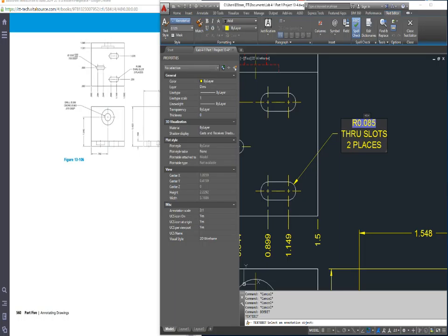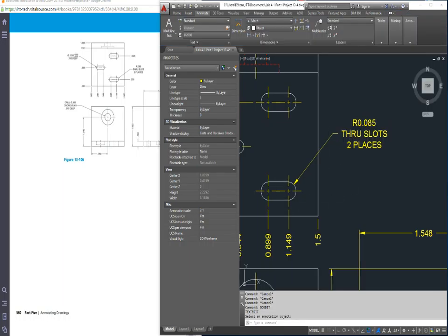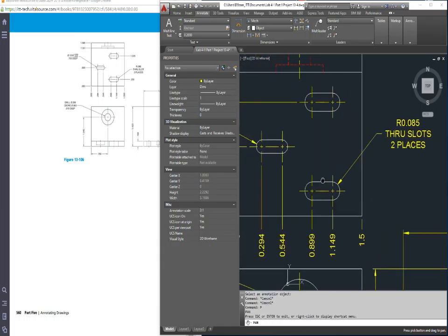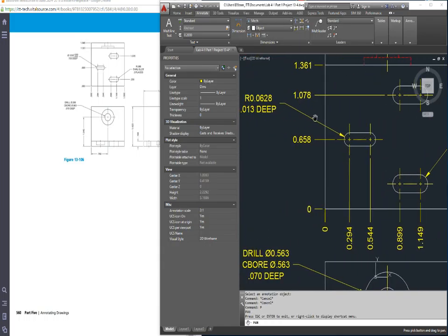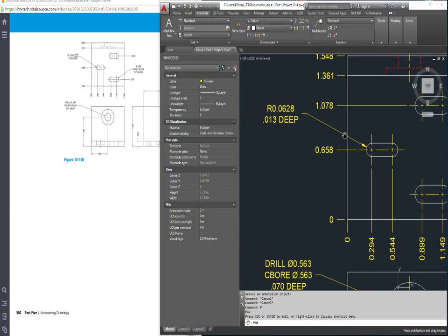That is annotated off of the arc or the circle, and that's the exact dimension that it is. And then I can just arrow before or after and type anything I want in that text box. So when you add this, you want to make sure that this leader line coming from the radius is not crossing any other dimension line.